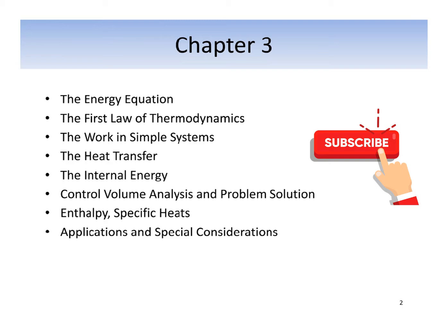Then we will discuss work and different perspectives of mechanical work because of rigid boundary motion or expanding boundaries. For instance, in the form of a rotating shaft, and the other one, expanding boundaries, covers the piston cylinder, for instance. The piston moves and the internal confined space expands. The work due to that force is known as work due to expanding boundaries.